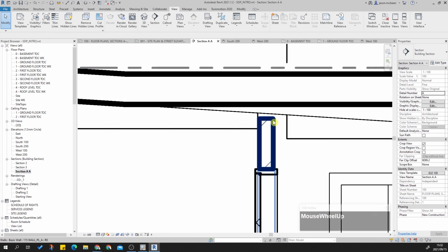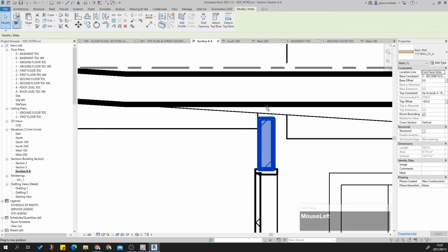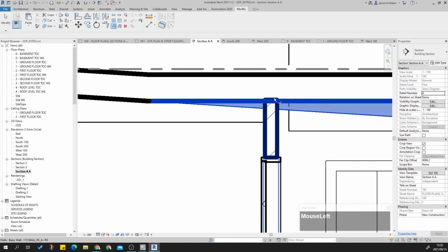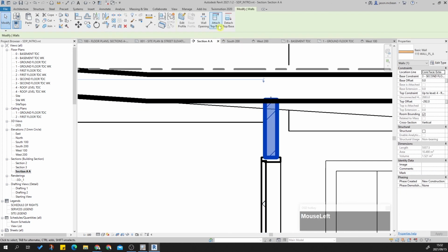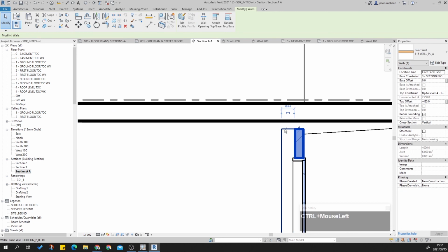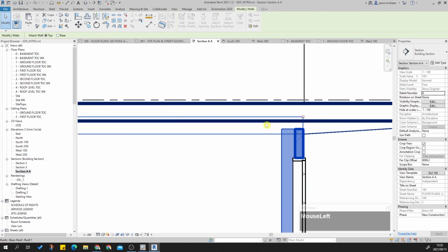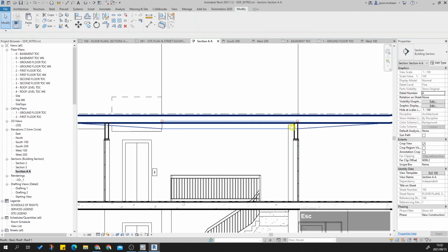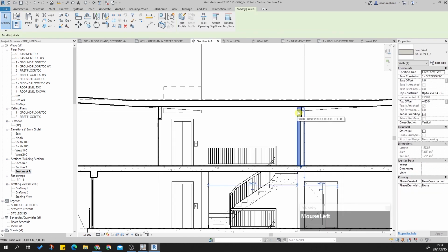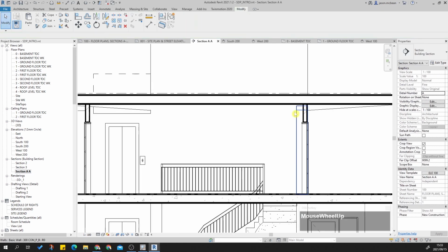And you can see these junctions where these roofs don't connect correctly. Okay, that's pretty straightforward. I can fix that. I can just say attach base to that. Likewise with this wall, there's a wall in the distance maybe that I just need to say attach base. Okay, but this is stuff that we can tackle later on. I'm not worried about that. That's a beam, I think. Yeah, that's fine.